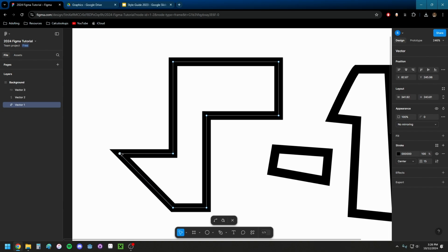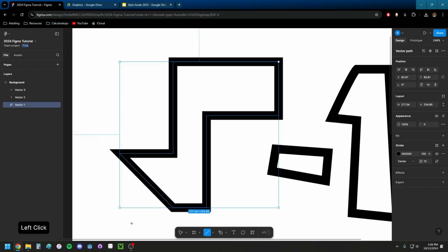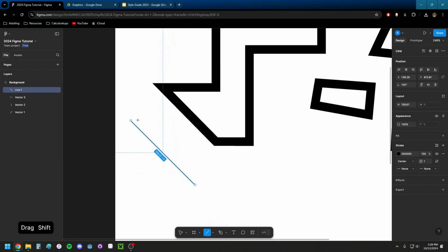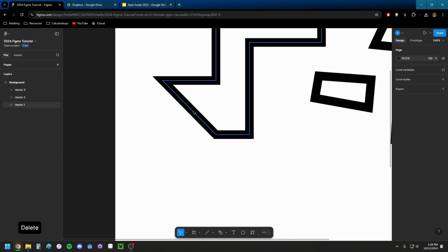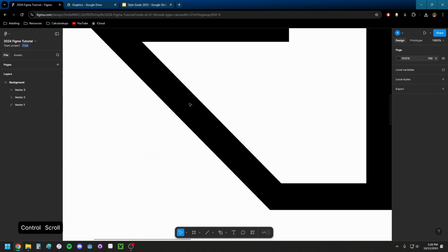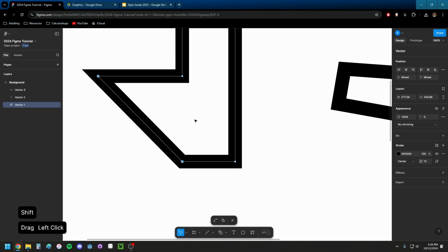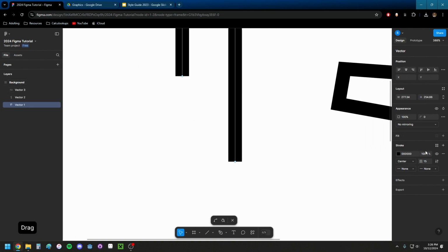Making a line exactly like 45 degrees can be a challenge at times. I would recommend going into the line tool, placing a line and holding shift. It'll snap it to cardinal directions. I say here, look at this line. Is it 45 degrees? Oh, is it 44? Is it 46? I don't know. I'm just going to delete these 2 nodes, holding shift while I do it. Delete them. It's gone. Don't worry about it.